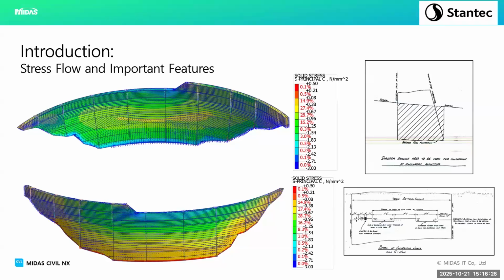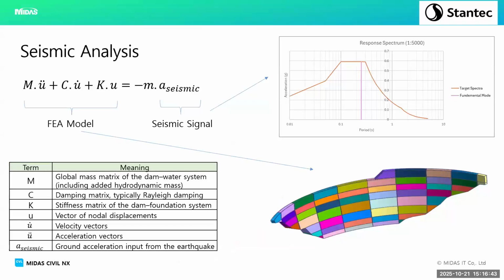And then another key point is the shear keys. So those are the vertical joints that have a shear key. So again, you want locking in of that hoop stress. So those are generally things we'd want to move forward and check.